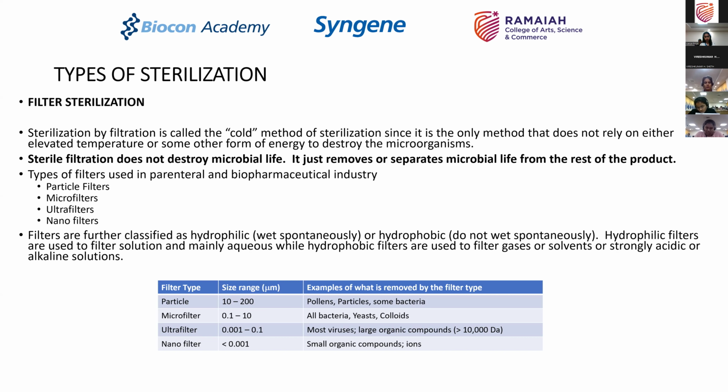Ultrafilter is 0.001 to 0.1. Most of the viruses and large organic compounds greater than 10,000 Daltons get removed by an ultrafilter, and nanofilter is less than 0.001 micrometers, very, very small organic compounds and ions.